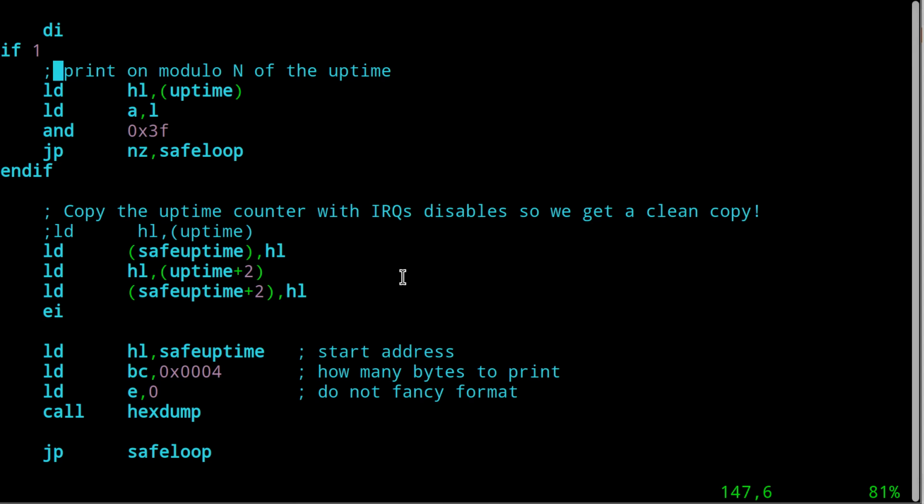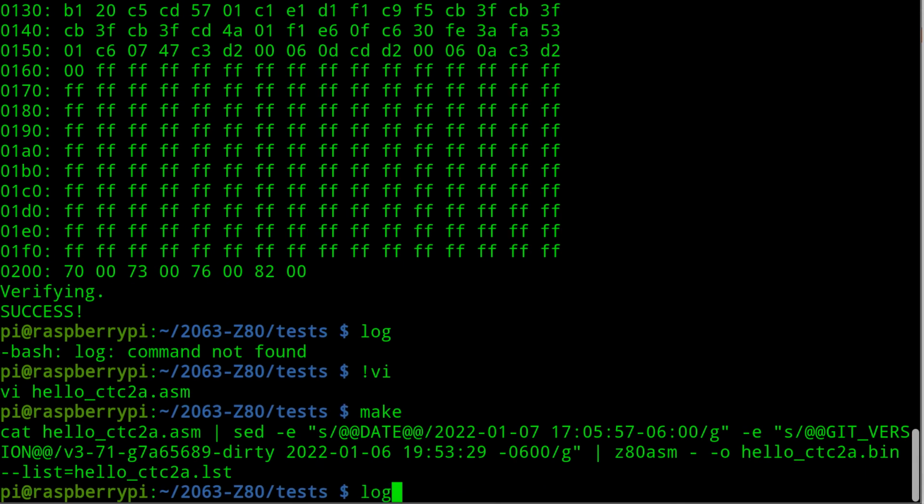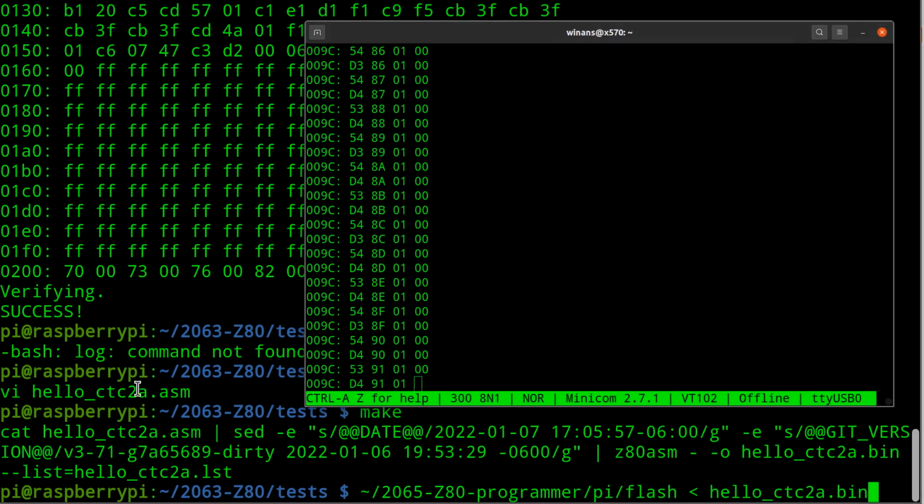Okay? Let's run this one and see what happens. Okay? Bring our terminal back in. It's still running the relatively crappy one. And you can also see we've incremented the high order bit here. When this thing rolled over, it must have gone to something or other FF, and then went and tested that other logic in the interrupt handler that dealt with that high order carry when we added the 1 to the 16-bit least significant word there, just FYI.